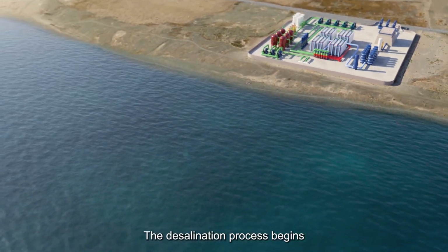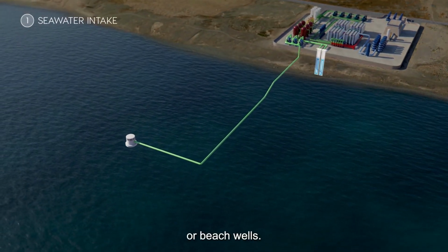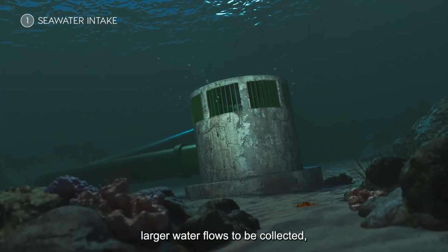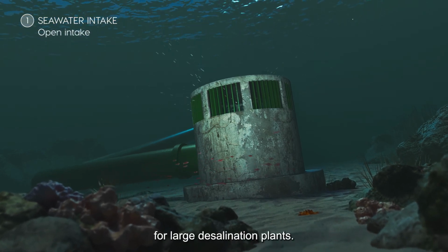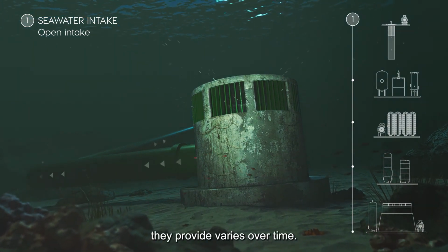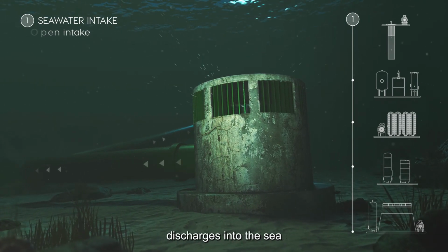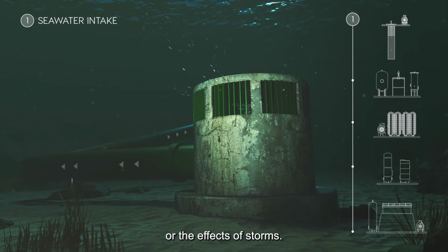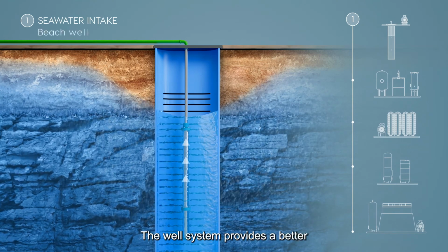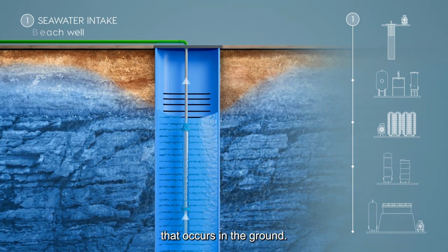The desalination process begins with a seawater intake, mainly through open intakes or beach wells. Open intakes allow for larger water flows to be collected and are therefore the most recommended method for large desalination plants. However, the quality of the water they provide varies over time. It can be affected by the presence of turbidity, changes in temperature, discharges into the sea, or the effects of storms. The well system provides a better and more stable quality of water, thanks to the natural filtration process that occurs in the ground.